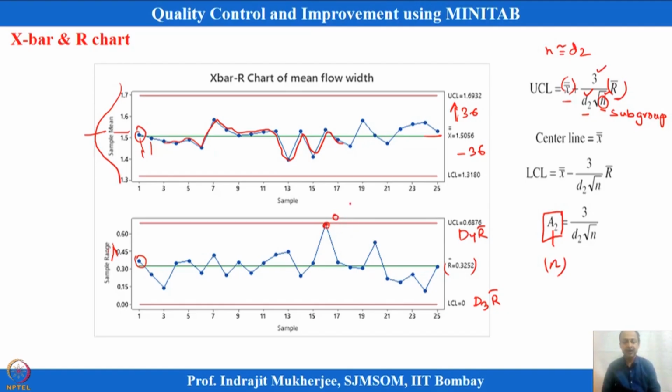On the line we will assume that this is in control scenarios like that. Okay. So, in this case also in x bar, when we are monitoring x bar, we are seeing all points are within the control limit line. So, natural variation. So, there is no abnormal points which go outside. So, in this case we can say that the process is behaving normally, and there is no abnormal scenarios.